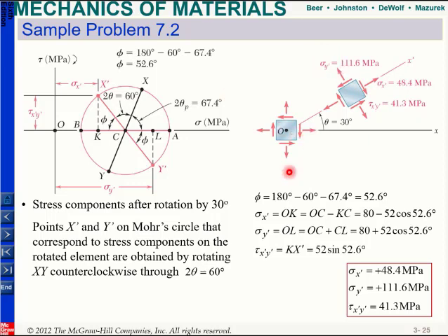Okay, and this is why the Mohr circle is a very good method where we can visualize what happens to our stresses when we rotate them. You have all the equations for rotations, so if you know your angle, like how much you rotate, you can find your stresses. But still, this provides a good idea of what happens if I rotate this counterclockwise to reach A, or I can also rotate it counterclockwise to reach B. And by visualizing this, I can determine what my stresses are easily.